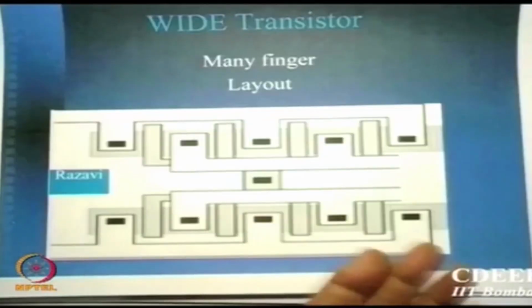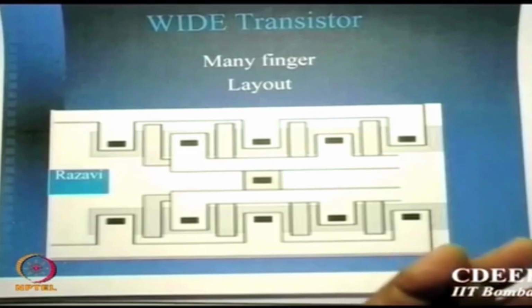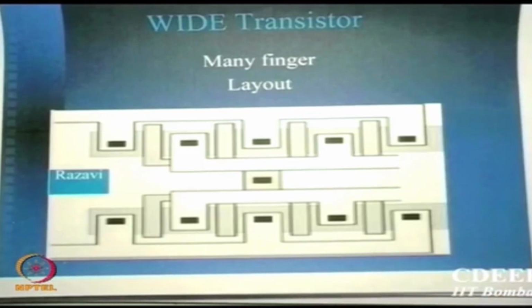This is called multi-finger transistors. The same statement which I made: if you have a very large width transistor, you can have two sets of them and in between connect. Multi-fingers and then connect together. Okay. So there are tricks for larger sizes, and again you can see it is trying to get into more symmetric systems. Our ultimate aim is getting symmetric systems.